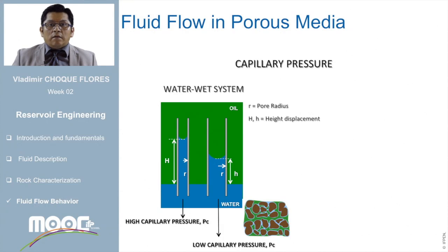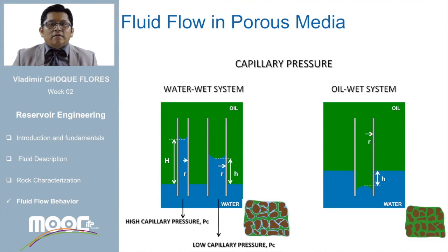In the same way, the wettability will be important in the displacement. The wettability represents the interactions between the fluid and the rock's surface. If the rock is water wet, the oil phase displacement will be easier, and the oil recovery will be higher. In contrast, if the rock is oil wet, the oil will stay attached to the rock, and the recovery will be lower. The recovery will be explained in more depth in the next lesson.